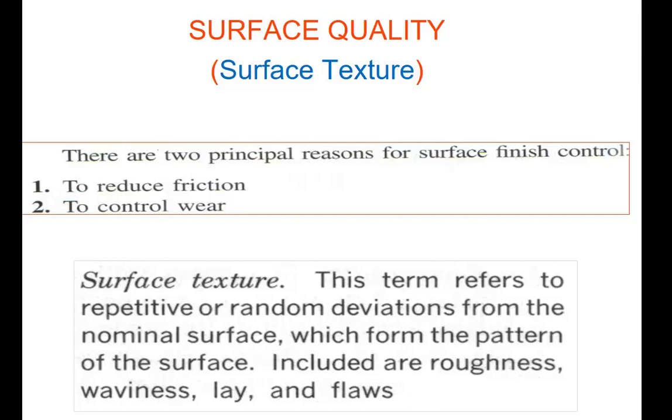Well, the irregularities of a surface can be controlled in size using the geometrical tolerance technique. If the size of the irregularities to control is in the order of millimeter, tenth of 1 millimeter, hundredth of 1 millimeter, and we want to control the form of the surface, the irregularities over the surface, flatness tolerance.